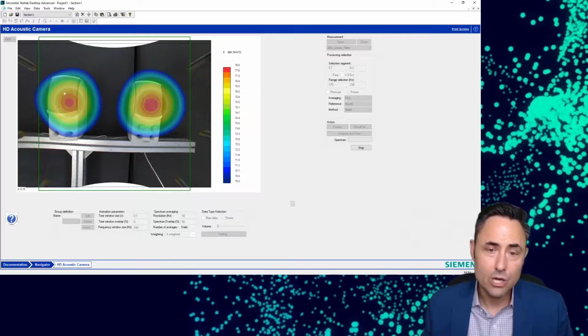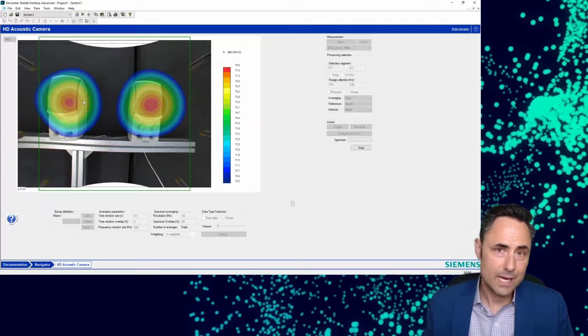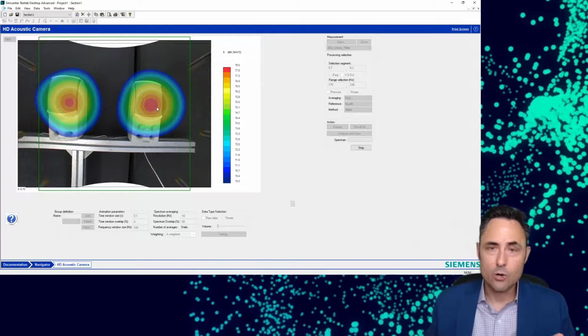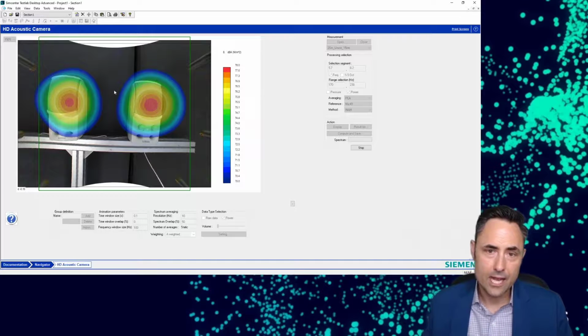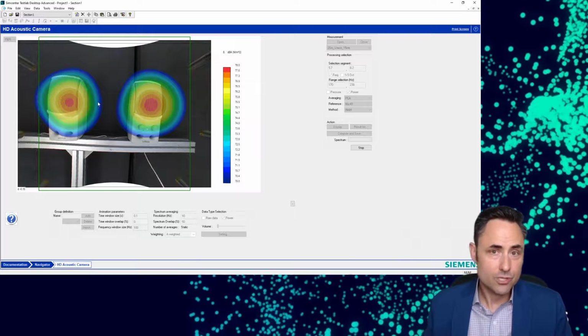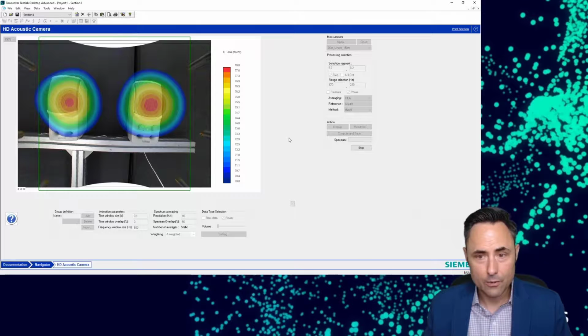I could tell you which of these speakers is responsible for contributing more of the sound power. So if I had an engine compartment or my air conditioner, with a compressor and a motor and some other component, I could rank the sound power contribution from each of these multiple sources using this algorithm. Okay, so very, very powerful.